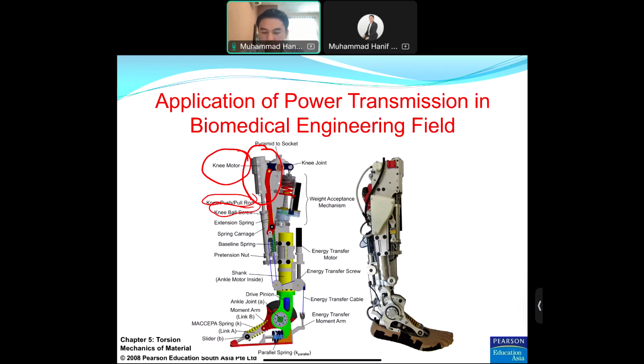If the shaft rotates at omega equal to 175 RPM, so this one is omega, but the unit is RPM. And it has an allowable shear stress of tau allowable equal to 100 megapascal. Determine the required diameter of shaft.